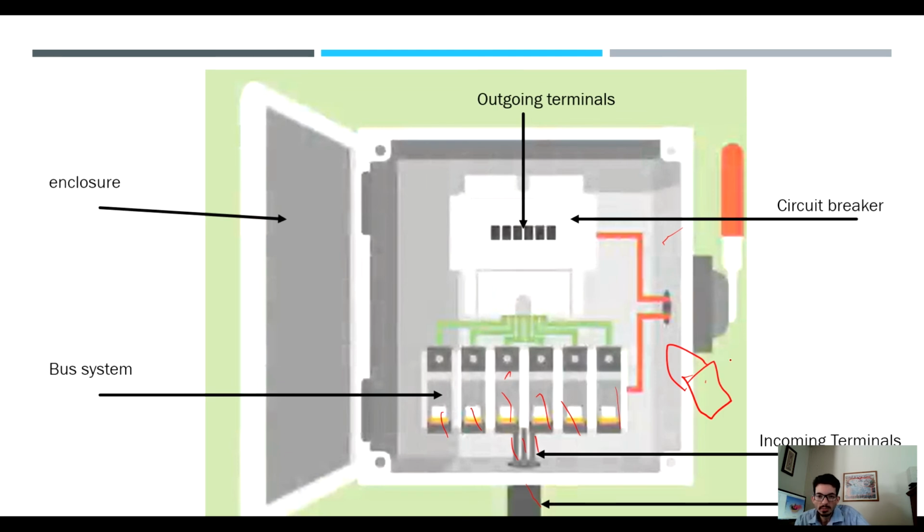This is extremely important, because when you are servicing machines, the panel has to be locked, and the unit can be serviced with no chance of electricity going through the system. You don't want the unit to start while you're operating, and you don't want the electricity flowing while you're changing a fuse, etc.